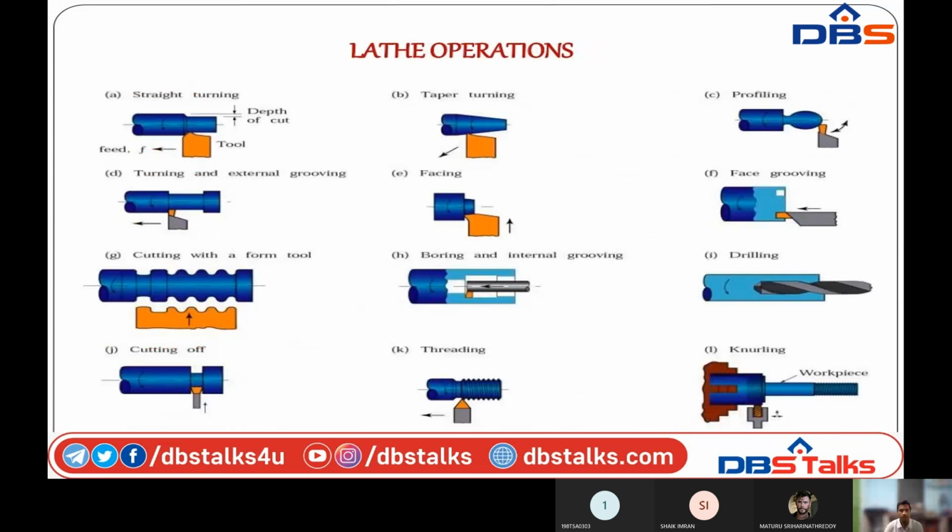Here are the different types of operations performed using a lathe machine. First of all, I am talking about straight turning. Straight turning or step turning means the tool is fixed at a perpendicular position to the workpiece. In taper turning, I am fixing the tool at an inclination to the workpiece.